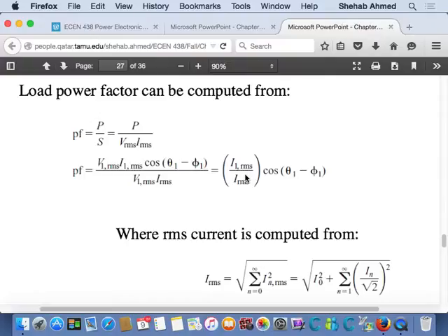How about if your system is fluctuating, if your amount of reactive power consumption is fluctuating? Then if you add a lot of capacitance to bring the power factor very close to unity, and you now lose all this reactive power load, what's going to happen to your power factor is it's going to go leading. And generators don't like leading power factor. Why? Because it reduces their capacity. In 459, we will talk more about that. The generators in the power stations would love unity power factor, which is not possible.